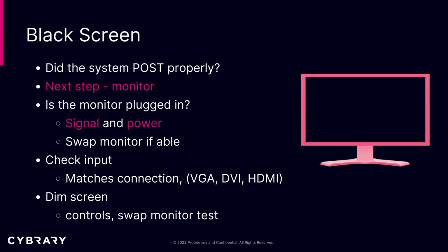Go ahead and check all your inputs. The type of connections could be VGA, DVI, HDMI. Check all those connections. If you had a dim screen, you can do the monitor test on that as well.